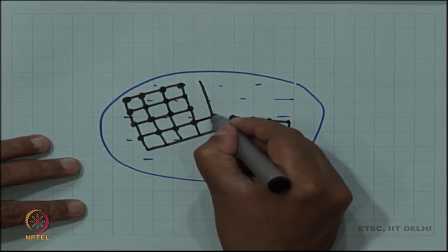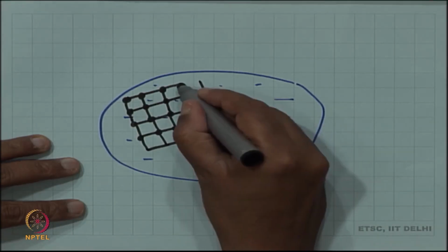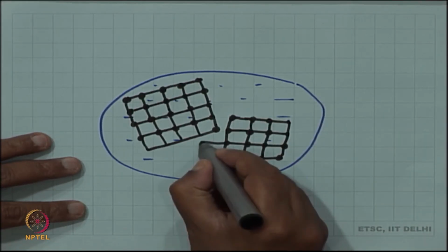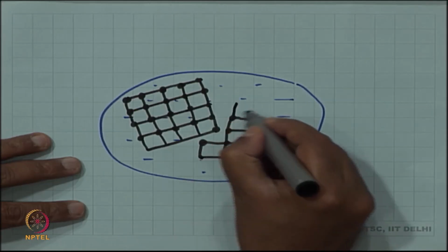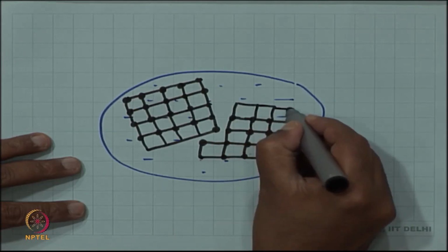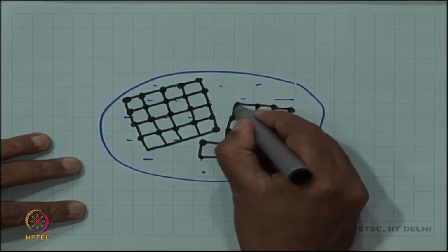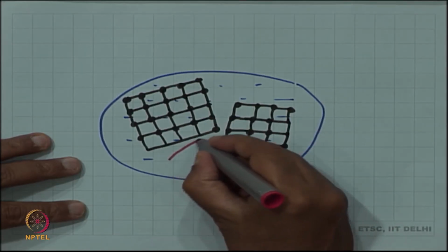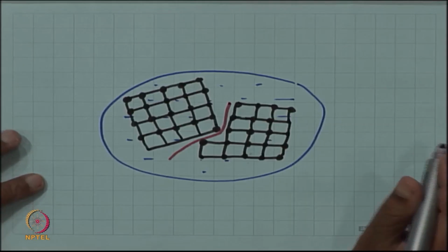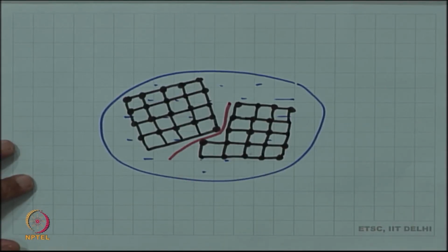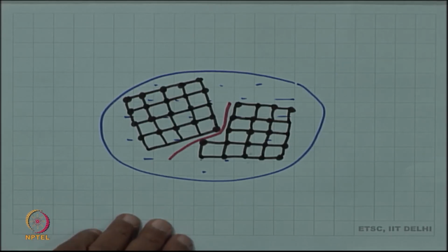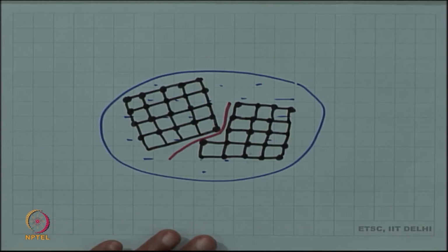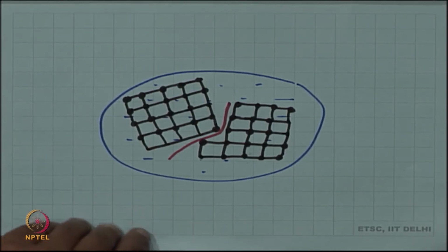In those regions where they meet, they will stop growing, and that is what will define the grain boundary, because the orientation will change in those regions. So, in this example where only two nuclei were growing, you can see that a grain boundary is now developing in this region. So, this is the reason why most materials are polycrystalline. Unless we take special care to make a single crystal, most materials will be polycrystalline.